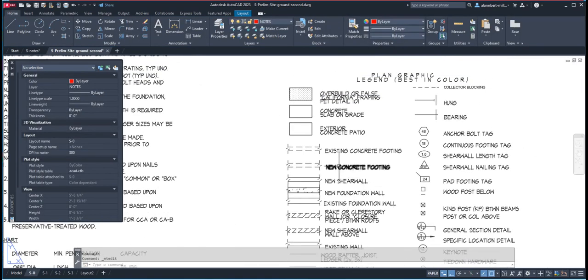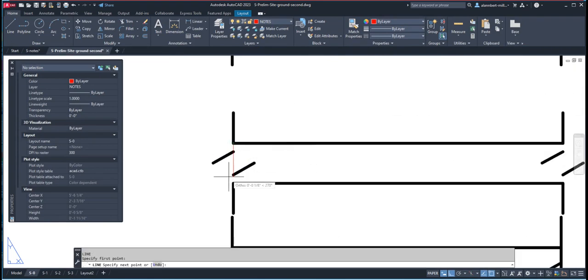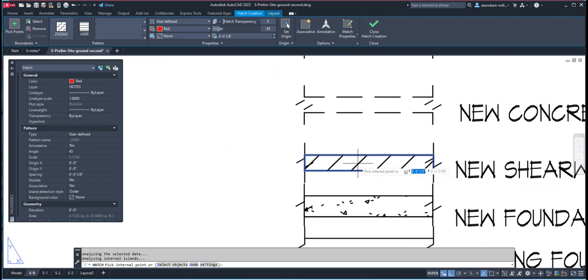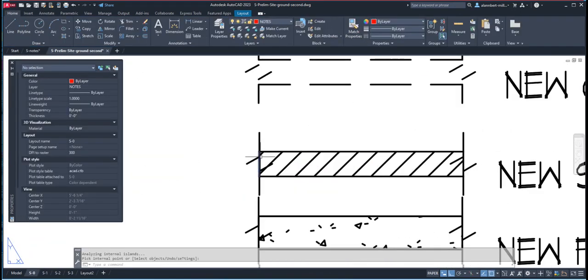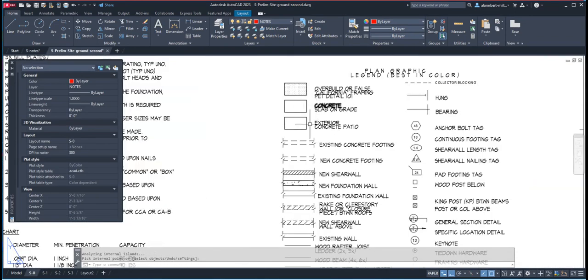All right. So this must match our shear wall. We'll just close this up first. It's a user-defined hatch, so we're gonna put a hatch, and we're going to put a user-defined hatch, and we're gonna set this at 45. I don't know if 1.8, yeah 1.8, but I want to change it to like maybe 130. I think that's it. That's better. Okay, so just click close, and then you can leave this hatch, but basically you have to make sure that this legend matches whatever you used.